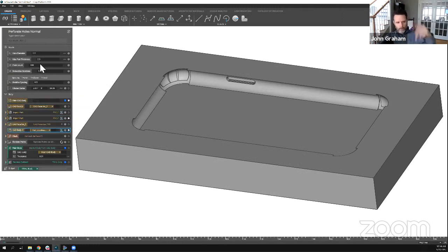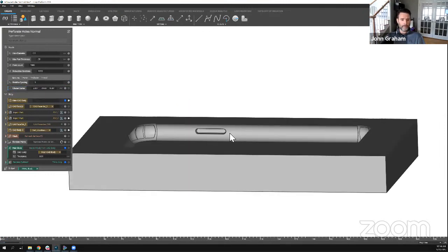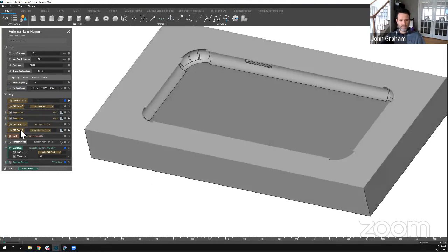Before I do that, before it actually rebuilds, let's put some variables in there that I know about or that I care about. I'll say my part thickness is only a fraction of a millimeter, because I don't want the holes to actually poke all the way through this. This is the mold. So I want something to happen to the texture, to the body itself. Let's increase the relative spacing to something a bit higher this time, because I want a void to go on this phone case, maybe where a certain logo might exist. Okay. And I think that's it for those variables.